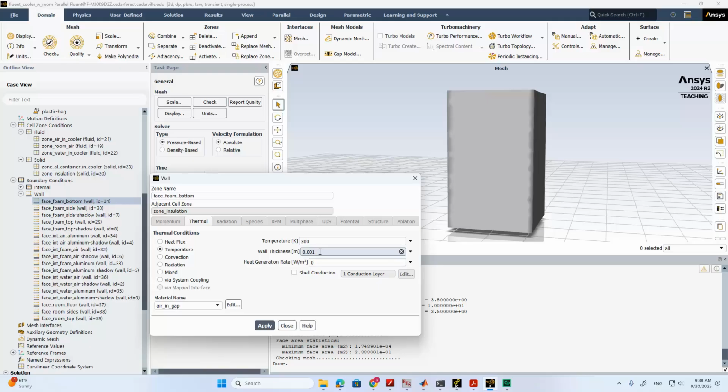Yeah. If the contact is pretty good, then we can reduce the thickness of the air gap. If the contact is not good, okay, the cooler surface is rough and the ground also has lots of roughness, so there are big gaps, right? Then we can increase this thickness.